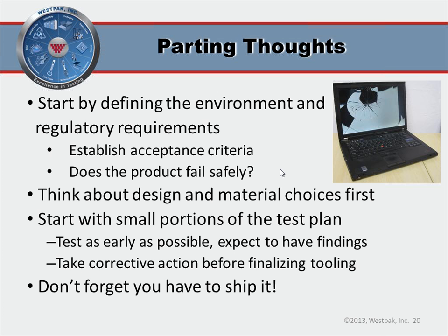Think about the design and materials choices first. As I mentioned throughout the presentation, a lot of these problems can be anticipated and resolved with good design. Start with small portions of the test plan. Don't jump into testing everything all at once. Start with things like temperature or vibration first. Test as early as you can. Expect to have findings. And then take corrective action on those findings before you invest in all your final tooling. And lastly, as Herb mentioned and I've mentioned, don't forget you have to ship it. Oftentimes that's the most severe environment.